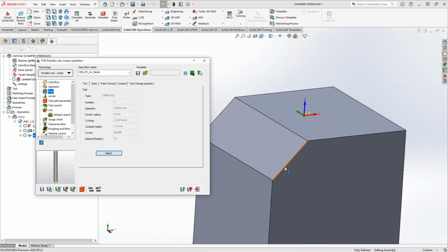Yeah, and even though Mark was using a chamfer mill before, this can also be done in a spot drill scenario too. So if you have that one-off part that you need to do, and you don't have that taper end mill or a chamfer mill, you can use a spot drill in there, as long as it's the right material. Obviously, we probably don't want to be tackling this with titanium or any of those harder materials, but that is absolutely optional.